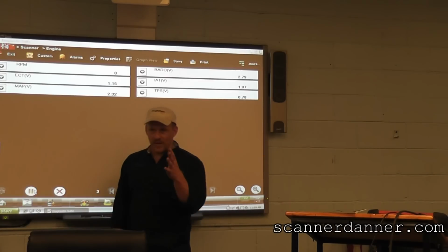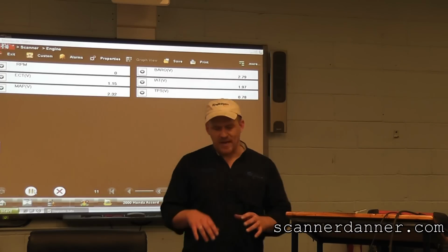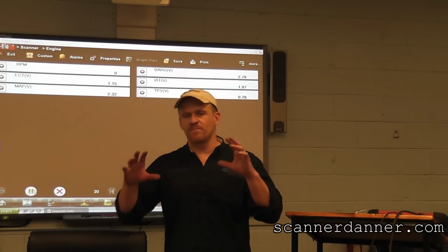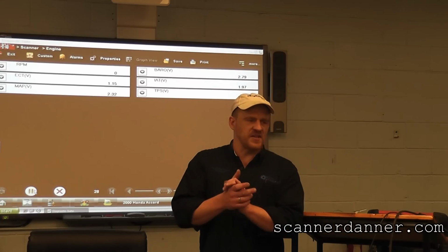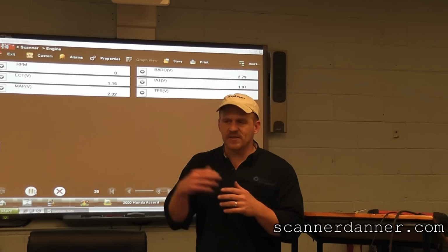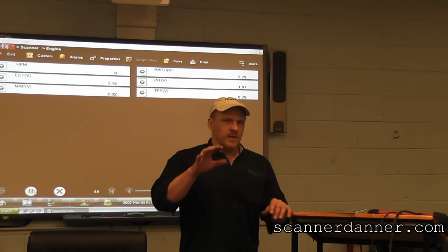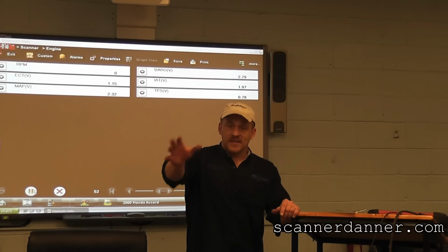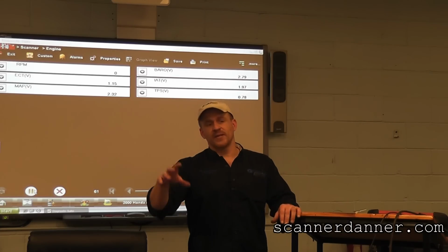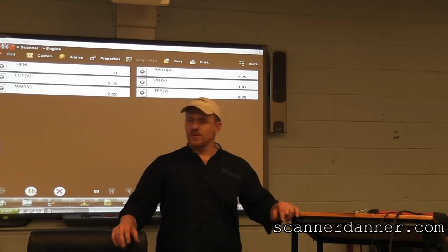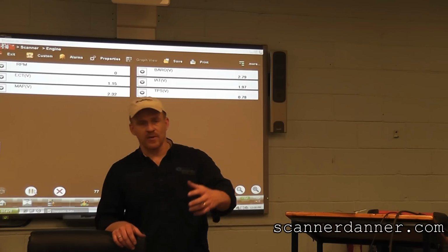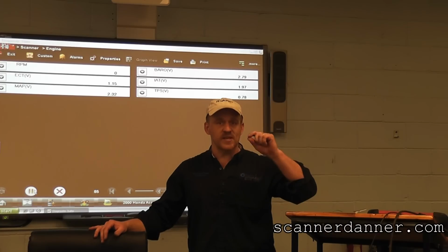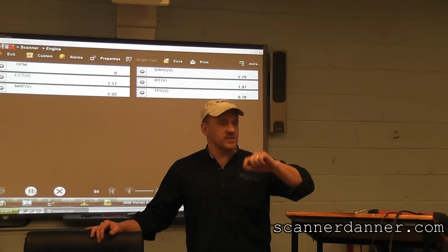One of the things I want you guys to be able to do when you start troubleshooting is have this checklist in your mind of major, critical sensors that we want to eyeball. This can be done very quickly, where we're looking at ECT, IAT, that's engine coolant temperature and intake air temperature, and manifold absolute pressure and throttle angle and barometric pressure. And we look at these and we say, that looks good, that looks good, that looks good, right?